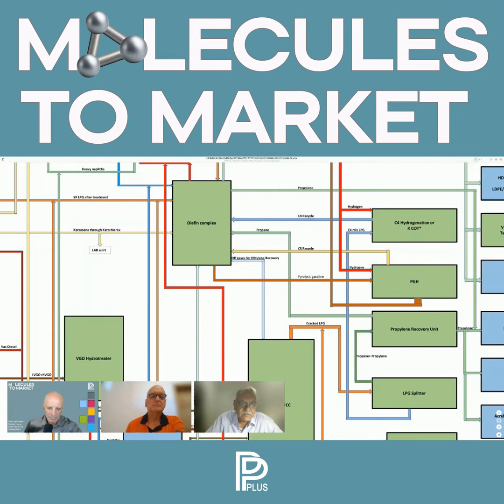For instance, I should look at the levels of the plant. So I must do a contour survey of the plant, work out the precise levels, and see how much I have to grade or level, or I have to fill earth into the plant to bring it to a certain level, and work out a cost towards it. If there is rock in the plant, I may have to do some blasting, rock cutting to level up the whole plant. I mean, all kinds of things.